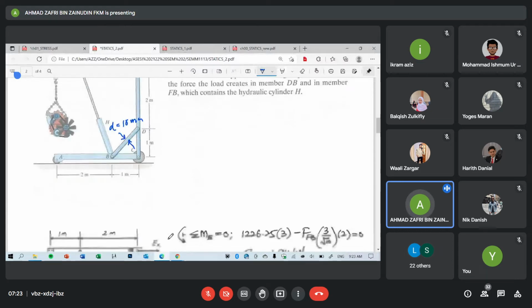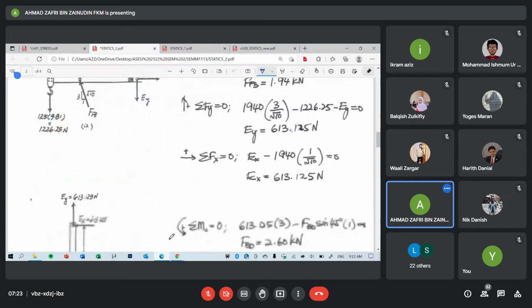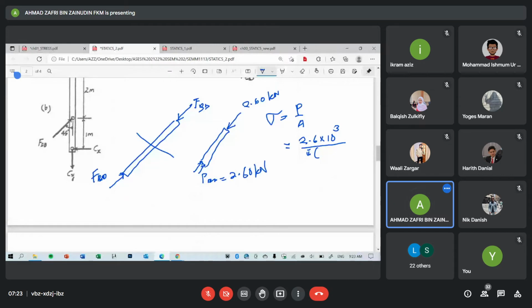Okay, let's use meters. How do I convert that 5 mm to meters? I want to use Newton for the force, so don't play with the units. So 0.005 meter, right? Squared. Pi r squared, so you get meter squared.